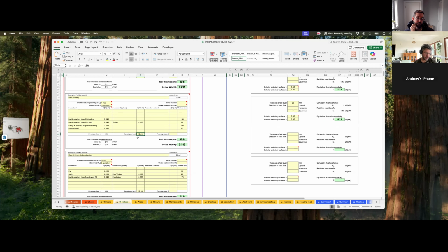So the idea is you'll have one penetration for each service, or a minimum number of penetrations, and then you've got a wall service cavity and a ceiling service cavity. And you run everything there. And do we seal them? Yes. So where you penetrate will be sealed off with tapes, or gaskets, or glue, or all three.